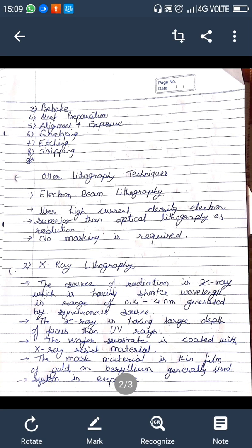Okay. The next step is developing. The mild alkaline solution dissolves the regions of photoresist which were not exposed to UV radiation. Therefore, metal is exposed in this region, whereas the regions of photoresist which were exposed to UV radiation remain intact. Developing is usually a wet chemical process. The wafer is immersed in the developing solution for a fixed time until the resist is completely removed, leaving the wafer material SiO2 uncovered.